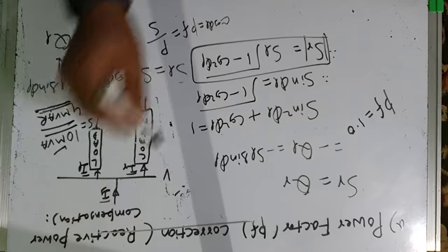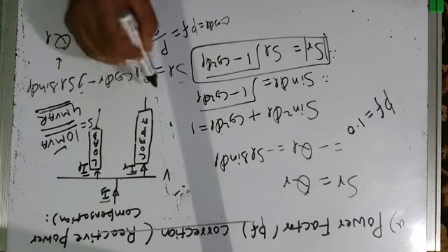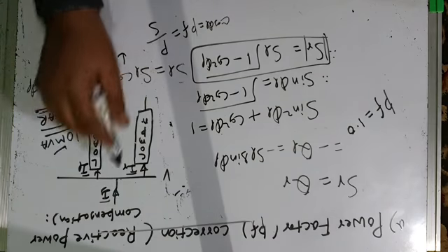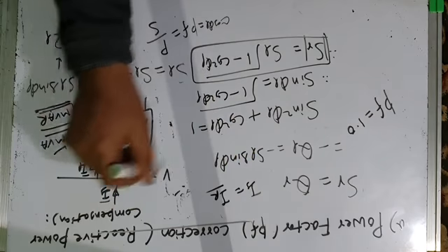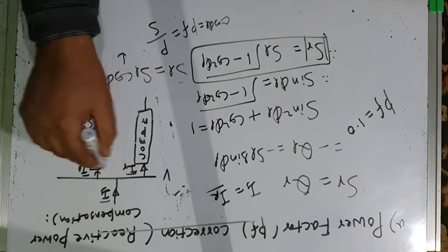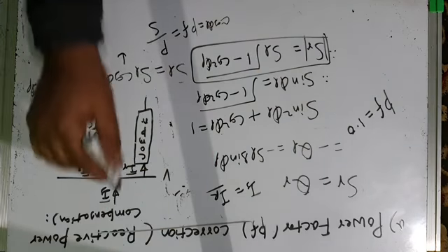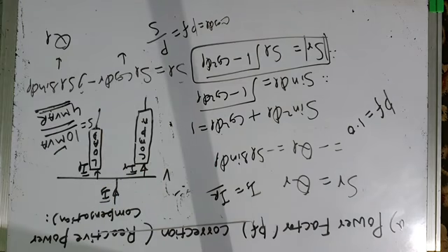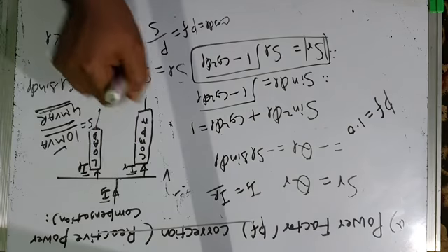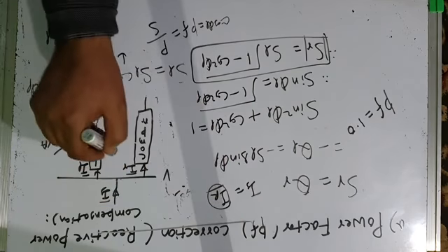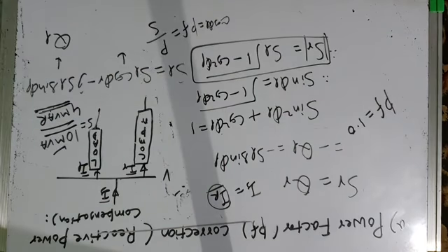और अगर लोड खाली एक्टिव पावर सप्लाई कर रहा है, रिएक्टिव पावर नहीं सप्लाई कर रहा है, reactive power comes from the compensator, so therefore the source current becomes only equal to the resistive component of current. It doesn't have to supply the reactive component of current. Therefore MVA rating generator, transformer, transmission line की कम हो जाएगी, and current also flowing in the generator, transformer, transmission line decreases. It is only IR, तो उसमें losses कम हो जाएंगी लाइन्स में, ट्रांसफार्मर्स में, और voltage regulation भी improve हो जाएगी, because voltage regulation is because of the voltage drop in the lines in the feeder, the load voltage में decrease. जब आप current ही कम कर रहे हो जो source से आ रही है because of power factor correction, so load voltage regulation भी improve हो जाएगी.